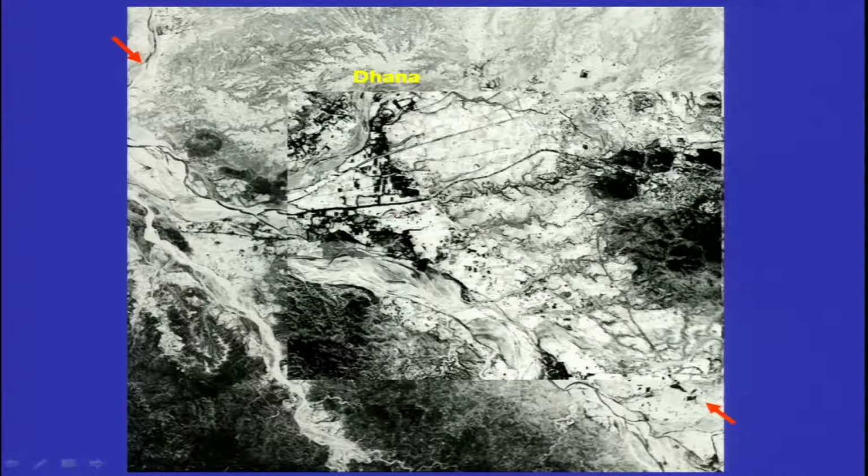So, this is a clear example that the block on the right hand side is the hanging wall, and it is getting deformed as compared to the foot wall on this side. So, this is your foot wall and this is your hanging wall, and then the fault trace goes somewhere over here. So, you can easily demarcate such features on the earth surface using the drainage pattern also. Channel morphology plays a very important role in identifying several such features.